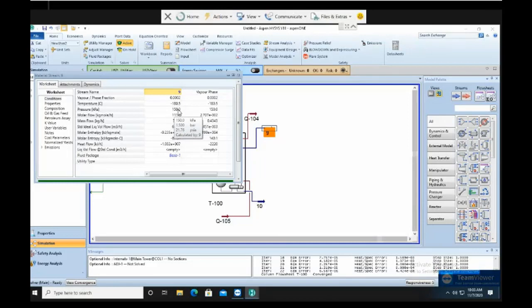But then you need a jet vacuum for the second DC. Usually we use vacuum DC because we want to protect the compound at the reboiler. If the pressure is too high, the temperature at the reboiler can go crazy, like 300 degrees Celsius, and it can actually destroy your compound.